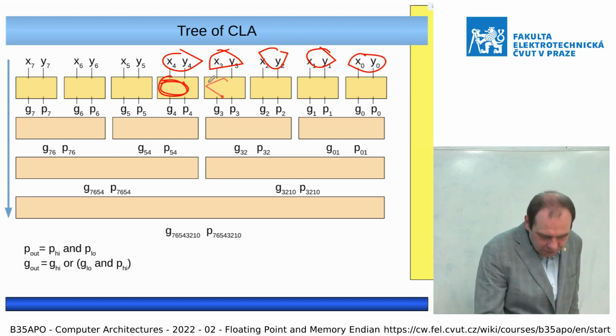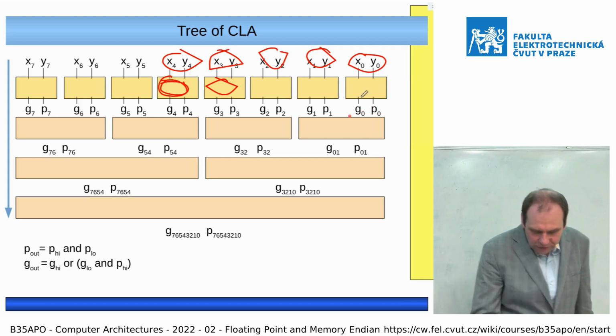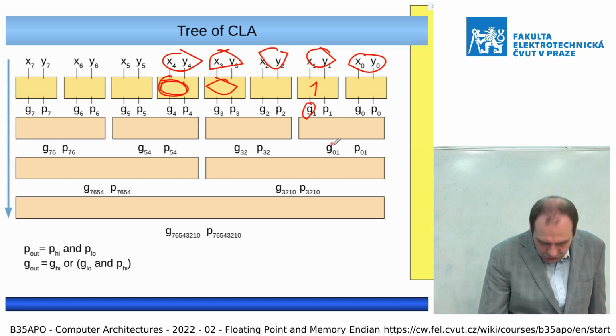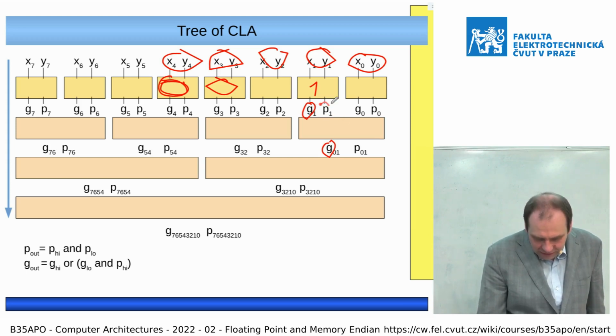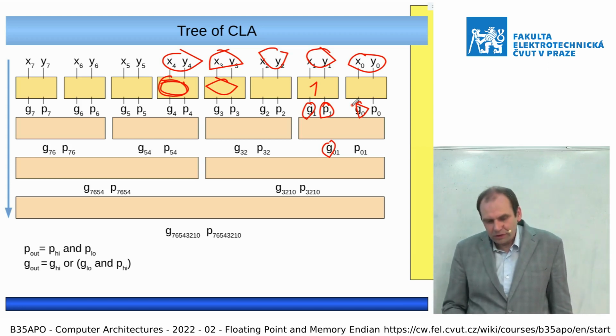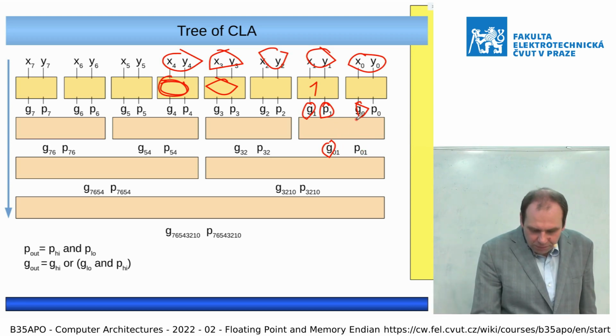For each bit we generate the propagate and generate, and then we can build a combination. Basically we know that if on bit 0 or on bit 1 there is no generation, then the generation will be 0. If there is a 0 on the propagation and the generation on bit 0 is a 0. So you can combine that generation and propagation logic for bigger blocks.